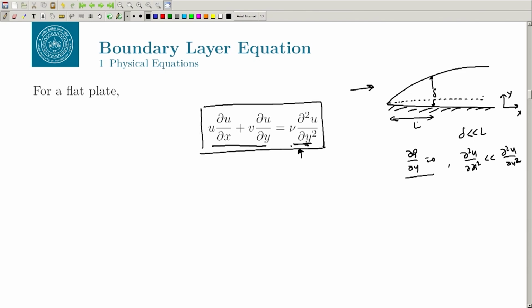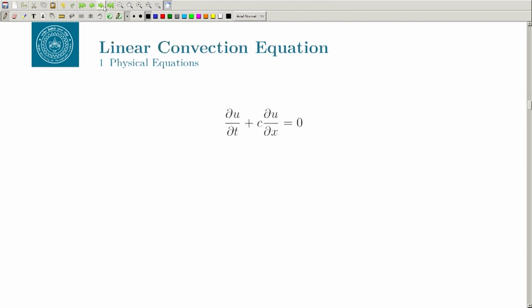Although you will have the gradient, you have to have the boundary layer, you cannot ignore it, no matter how high your inertial force is. You will have the gradient changing, with the velocity going to 0 here and going to u infinity here. This distance, the delta, may become very small, but delta has to be there. We will look at the nature of this equation also when we go to the classification of the PDEs. Right now I am just describing the equations that you already know.